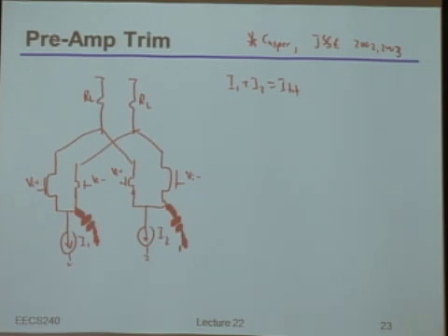Like, how big were your signal swings? Say that again? Tens of millivolts. And when you do the 5x larger than that, it becomes, let's say, 100 to a couple hundred millivolts, right? All right, well, if I need a couple hundred millivolts of offset, and we'll see why in a second, I will most likely need to steer the current almost fully to one side or to the other. What's bad about this circuit when you steer the current fully to one side or the other?